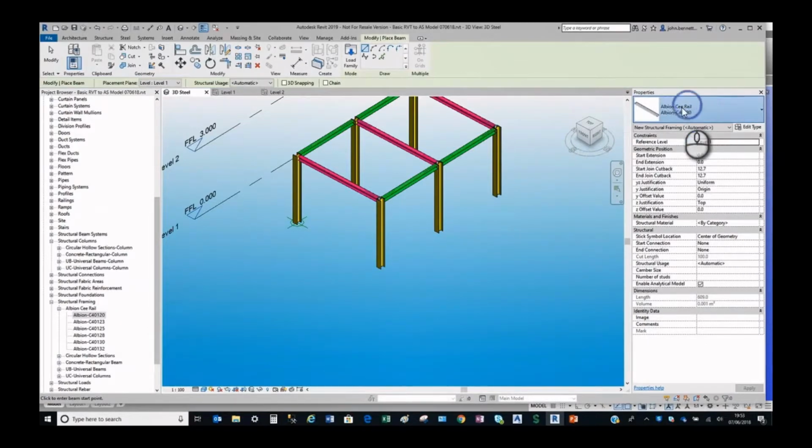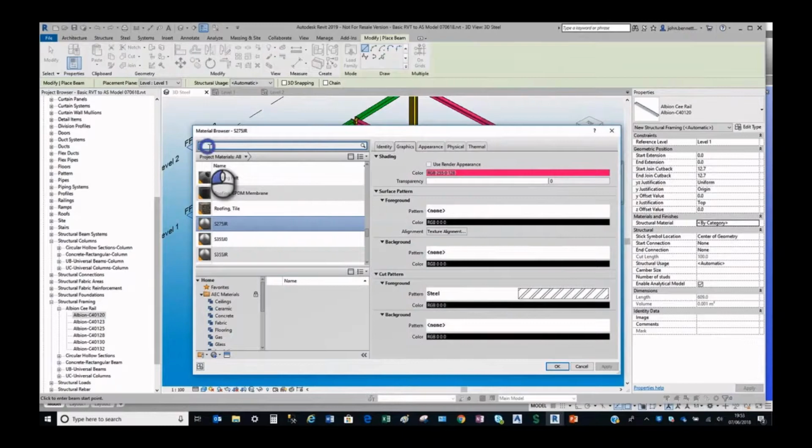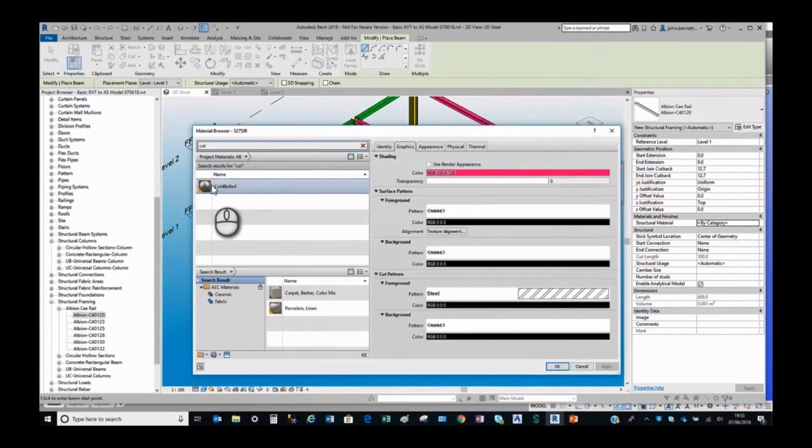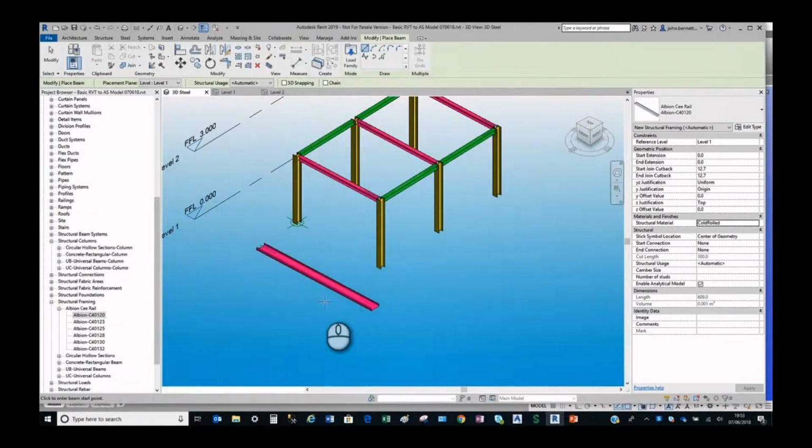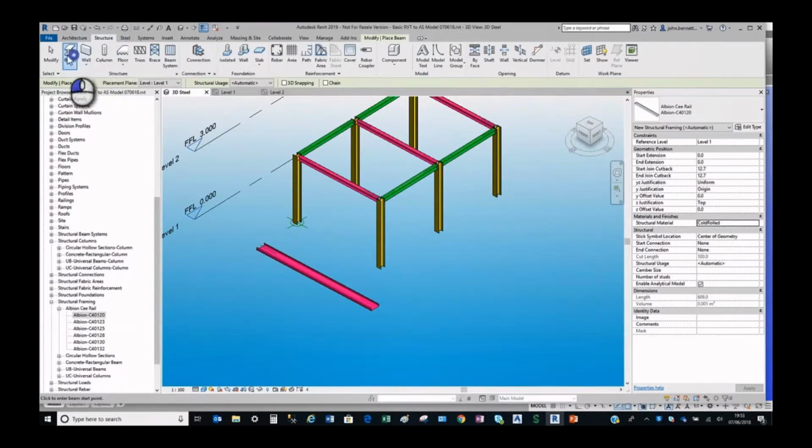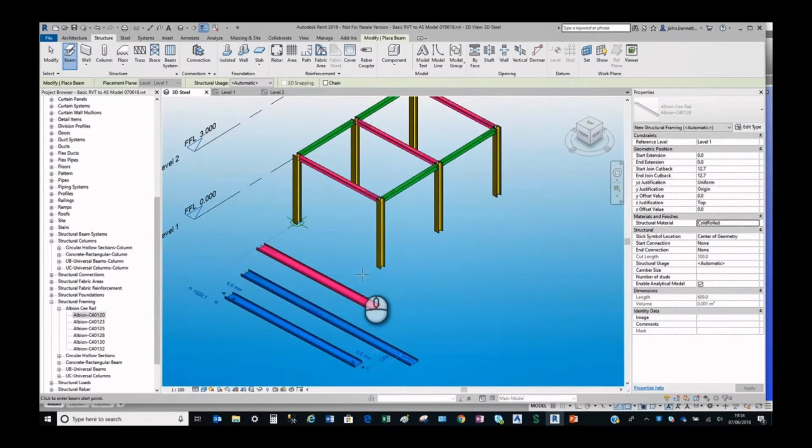So you need to have the corresponding structure inside Revit for it to come across correctly with the correct gauge and material sizes. So I'm just drawing a beam here initially. I just picked this supplier because it was one that I found. It could have been any supplier, providing they had a family, or you could have created it yourself if you wanted to. Obviously, a little change in material there. You'll see the original material is different, but now if I go back and draw a section, it should draw it with the cold rolled material. I'll come on to talk a little bit more about that one because that's quite an interesting analogy as well. That's because we use cold rolled as a material inside Advanced Steel.